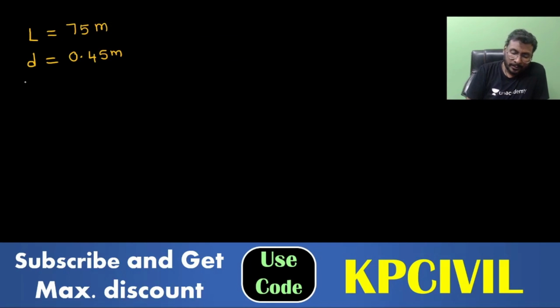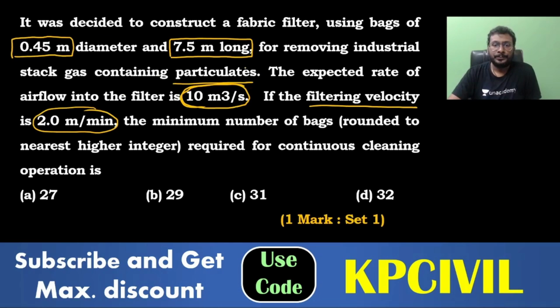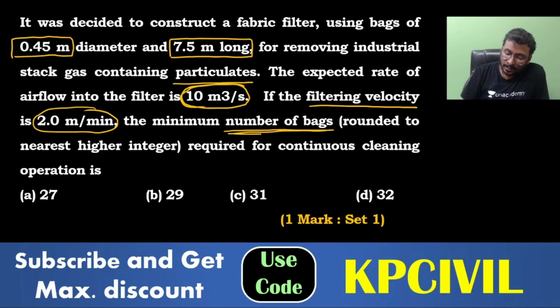So we'll write down discharge 10 meter cube per second. Velocity 2 meter per minute. So I am converting discharge also to meter cube per minute. 10 into 60 meter cube per minute. Good. Minimum number of bags required for continuous cleaning operation. Number of filter bags required.